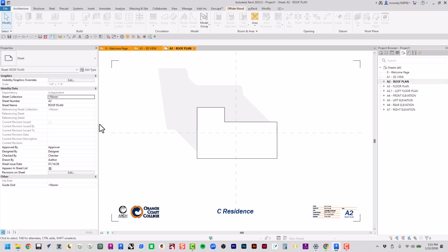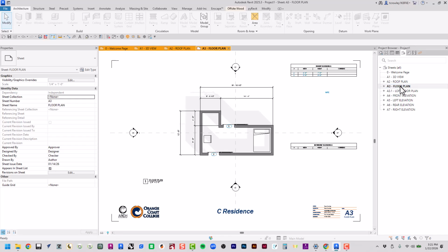The next sheet, floor plan, focuses on your floor plan, right? And when we say floor plan in architecture, we mean doing a horizontal cut through our 3D model, right? Through our home, through our building. And that horizontal cut typically will start at about 4 feet in height. So if we look around this room that we're in the studio, if I were to say, let's cut it at 4 feet,